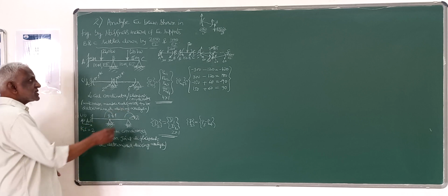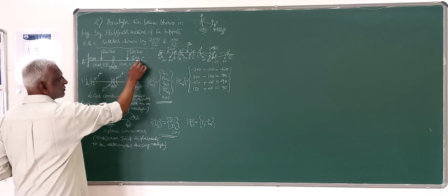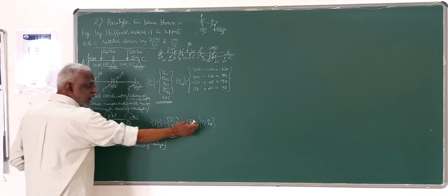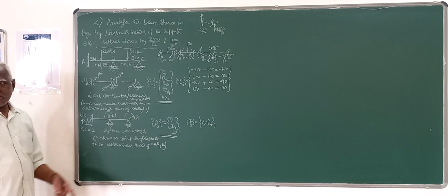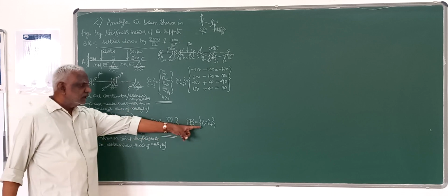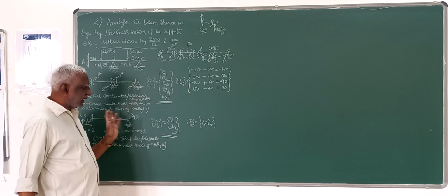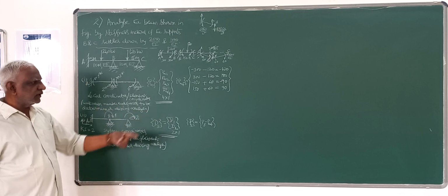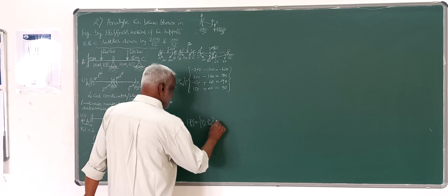In the previous class you saw a problem, the overhang problem. Due to that overhang there was a joint moment. That moment I was taking as it is, but here there is no overhang or any joint moment at the corresponding coordinate, so it is straight away 0.